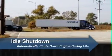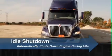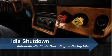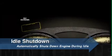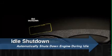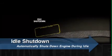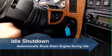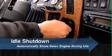The Idle Shutdown Timer, or IST feature, is designed to automatically shut down the engine during extended idle time periods. When the vehicle is stationary and the parking brake is set, the IST system starts a timer. A visual indication will signal 30 seconds before engine shutdown occurs. This will continue until the engine shuts down or the idle shutdown timer is reset. Your fleet manager can enable features to allow you to stop the sequence, or if shutdown completes, you can key off and key back on to restart the vehicle.